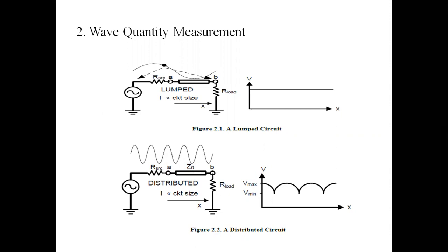While measuring with simple volt and current meters, we are able to determine the impedances and transfer functions of circuits at lower frequencies. Measuring similar characteristics at higher frequencies requires the measurement of incident and reflected waves. In fact, a VNA is able to measure the amplitude and the phase difference between the individual waves using one of the waves as a reference. Modern VNAs are even able to measure these quantities in an absolute way instead of a relative way.